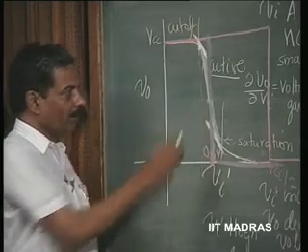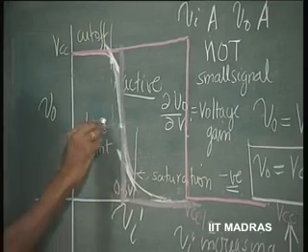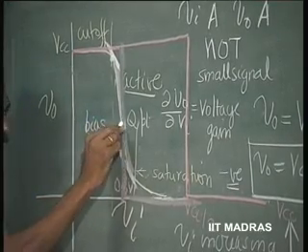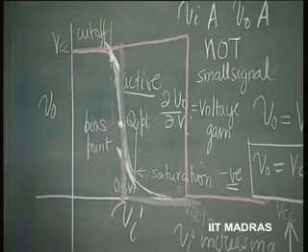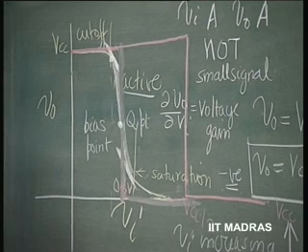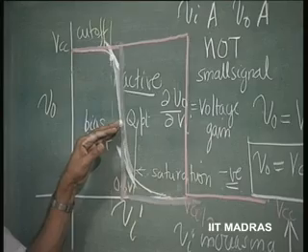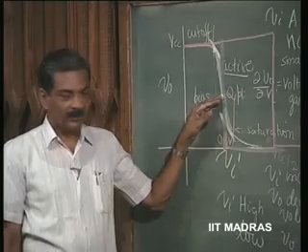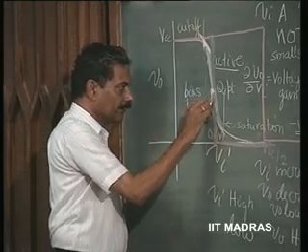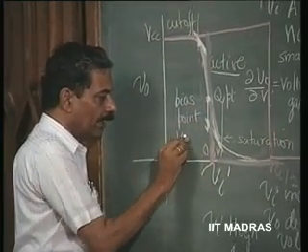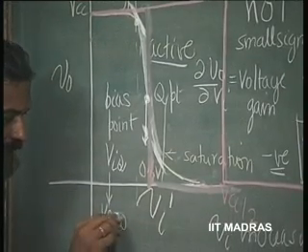Now, if it is operated at a certain operating point for using it as an amplifier, then at that particular operating point, bias point or operating point or Q point, we have a voltage which is a DC voltage, over and above which we can superimpose our time varying signal. So, this has a constant voltage. This voltage we will call VIQ, which is nothing but VBE quiescent.